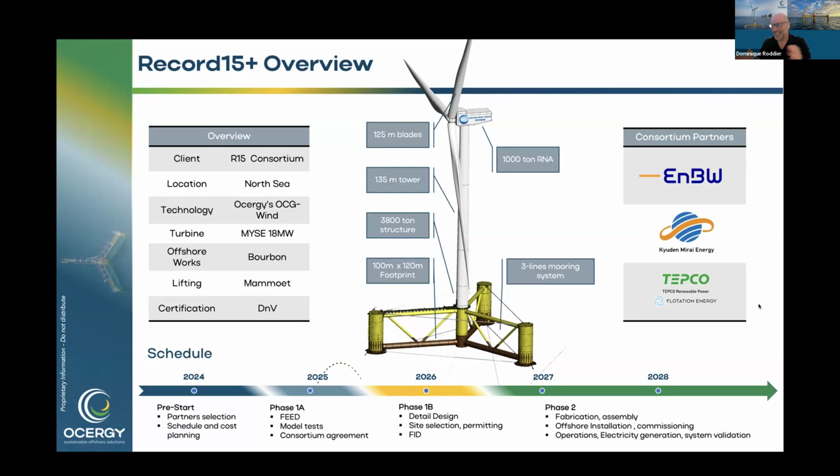In the Med, there's either no wind or a lot of wind. But we're also seeing capacity factors offshore in the 45 to 50% range. In terms of average wind speed, 10 meters per second is a very, very good site. We can do projects anywhere between 8 and 9, and lower is difficult.